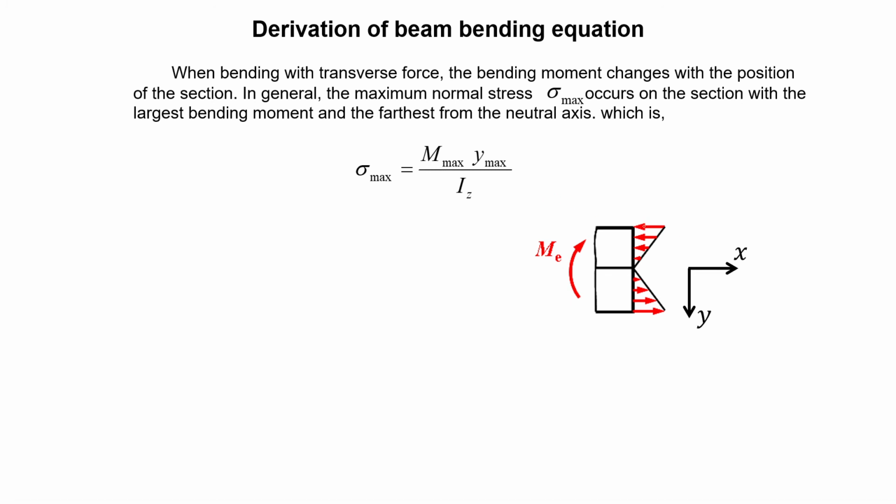As I mentioned already, and also from the arrow here, you can see on the edge you will get the maximum stress because y is the max at this stage. Similarly, in either tension or compression, y will characterize the stress because the moment is fixed and Iz is fixed.